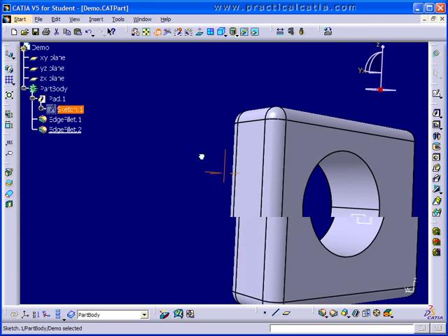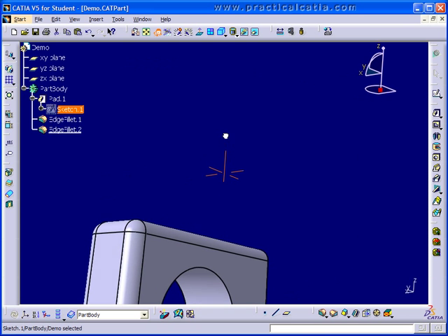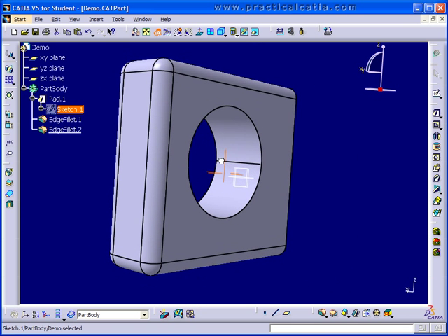And in essence what I'm doing is I'm viewing the object as though I'm moving my head left and right, up and down. The minute I release the mouse button, the icon or the tool releases. Now next to that is fly mode. Next to that is accelerate and decelerate. Now you'll want to play around with these because by default I think it wants to accelerate pretty quickly. So let's click on decelerate a little bit here, a couple of times, 3 or 4 times.